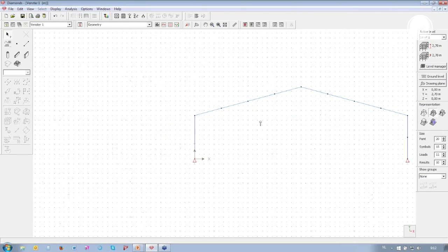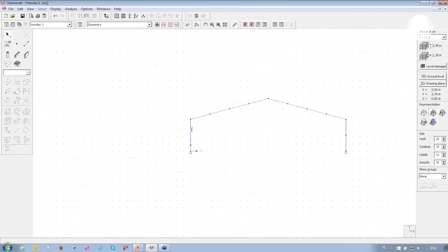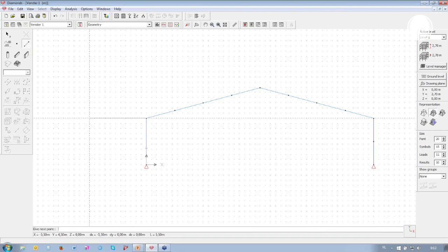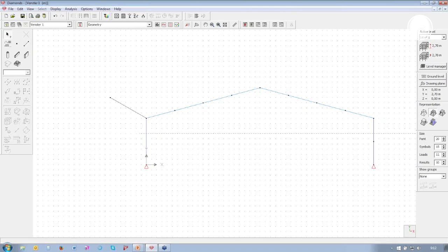Now we will add the smaller part on the left side. So how will we do that? Well, I'm just going to create a simple line which is not even close to what we are looking for. Just drawing it and leaving the drawing function with escape. Now I will double click this line to edit the properties, and as you can see, 2 little blue parallel lines appear, which means that at that point the mouse will snap to the line to double click it. So that's very practical. You can also see a similar phenomenon when you are approaching a node.